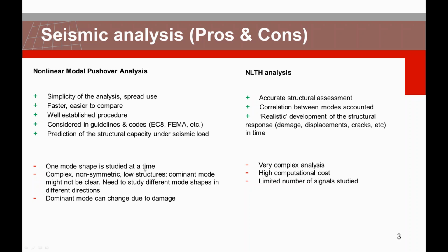When we have symmetric tall structures where we know the dominant mode, no problem. But if we have complex and non-symmetric low structures, this dominant mode might not be clear, so we need to study different mode shapes in different directions. Also, this dominant mode can change due to damage, and this is not accounted for in the pushover.